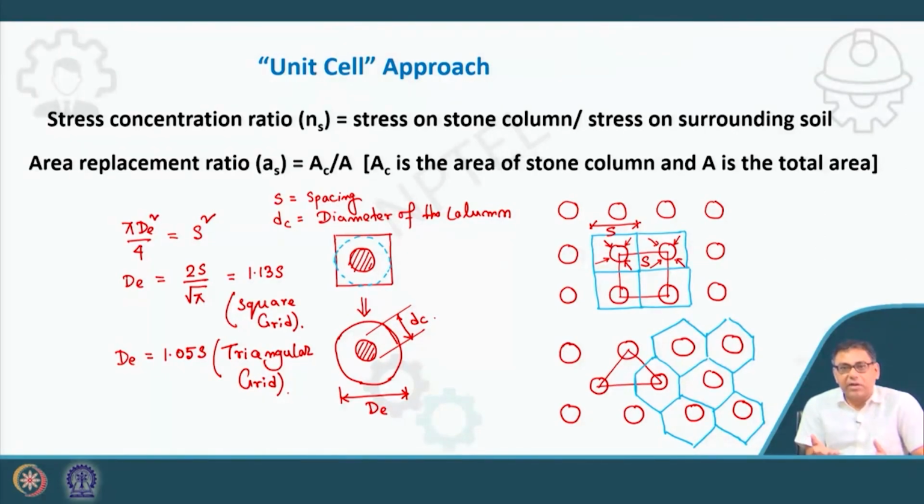So instead of around 10 meter, it now comes down to 1.5 meter and travels radially. This is true for consolidation and liquefaction also. The travel path is reduced, so the pore pressure will be dissipated at a faster rate. That is one reason: the travel path is reduced because of this lateral drainage.